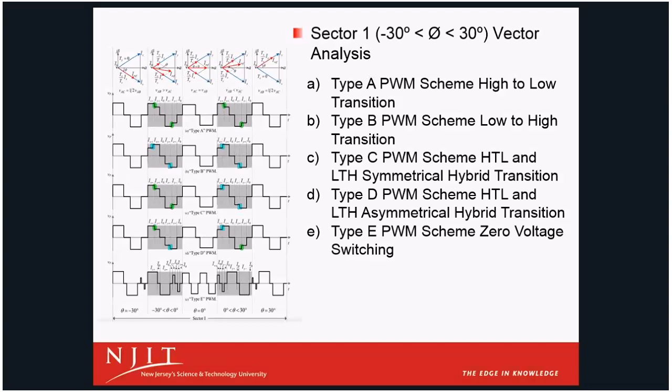So this is a more detailed diagram showing the different phases of the switching cycles for a 60-degree segment of your 360 full cycle. And up top it describes the different conditions that the rectifier is seeing and how it makes its transitions to get you your different transformer primary voltages in order to get your DC voltage at your load.